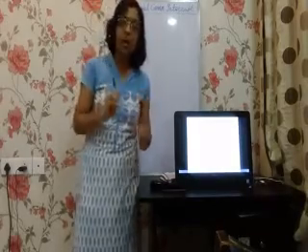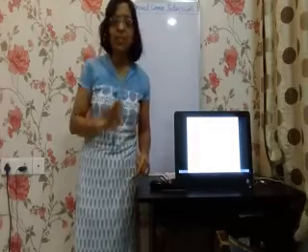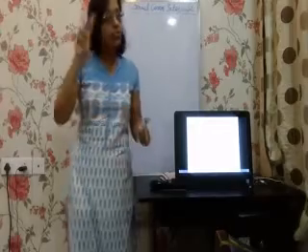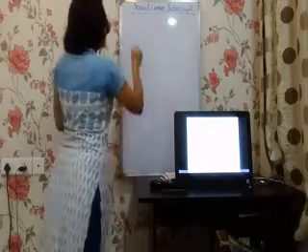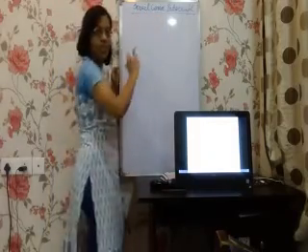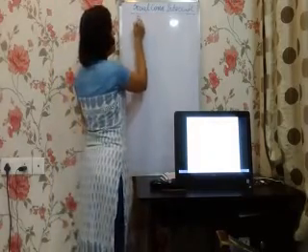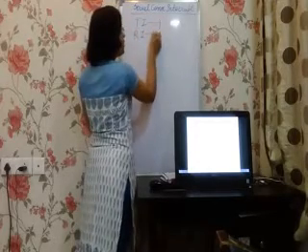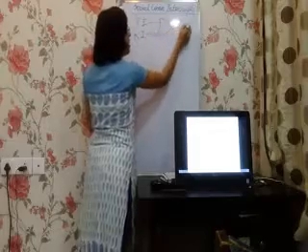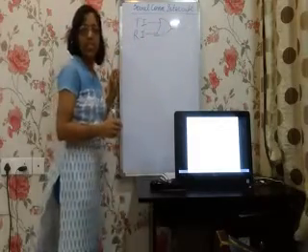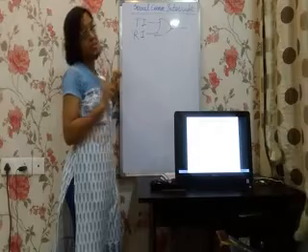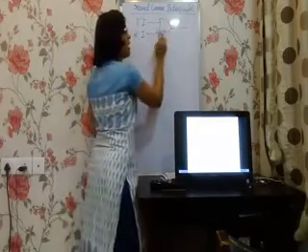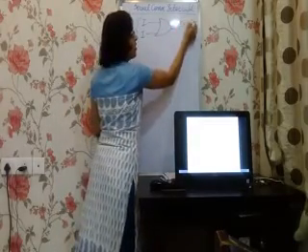Now, keeping all this in mind, let us see how serial communication interrupt works. Though there are 2 flags in serial communication, one for transmit and one for receive, we have only one interrupt for serial communication. The TI and RI flag bits both have to be checked to understand which of them has invoked the interrupt. And what will be the ISR address? The ISR address will be 0023H.